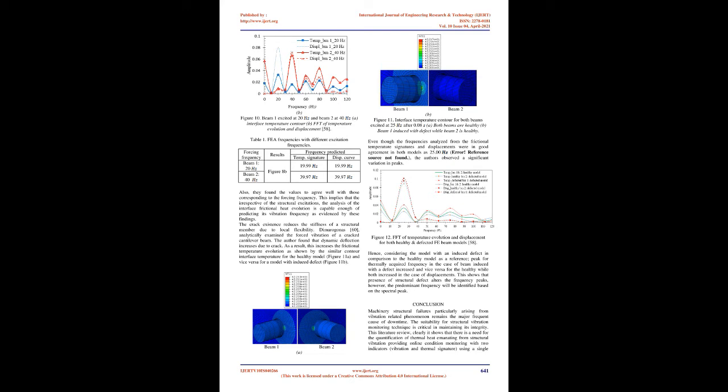Therefore, the vibration frequencies evaluated for beam 1 and beam 2 were 19.9885, figure 6a, and 19.9973, figure 6b, respectively. These were in good agreement with those measured using the accelerometer, with the relative difference being 0.26 and 0.21 for the former and latter, respectively. The several smaller frequency peaks observed with beam 1 were associated with the beam multidynamics due to periodic loading.